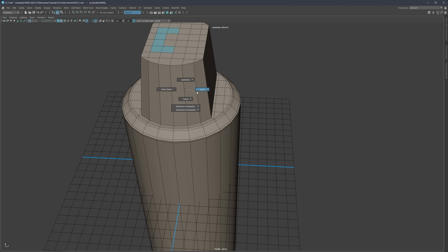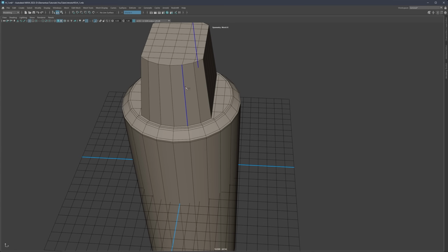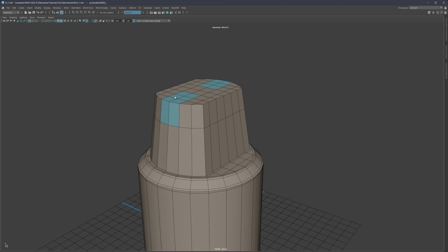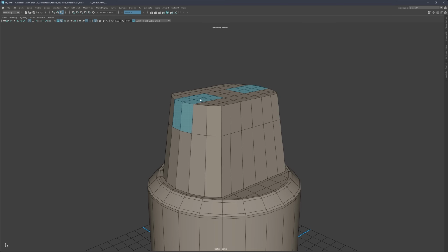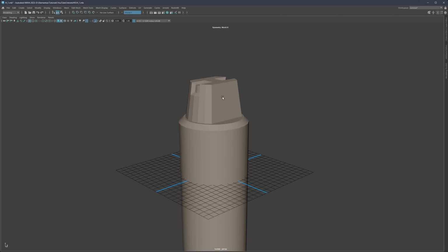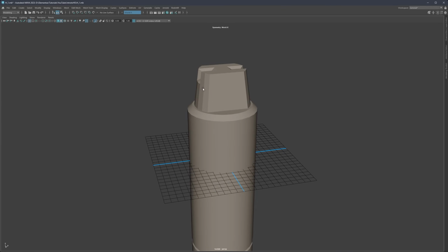Let's go to multi-cut in the object mode. Multi-cut is going to be here. Let's say create cut, Q to confirm, go to face mode. And again, just trying to improvise on the spot. Let's hit scale tool and maybe holding shift and extrude on the inside. And we're just trying to find positions or places that we can break that surface.